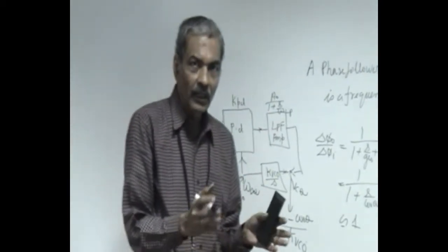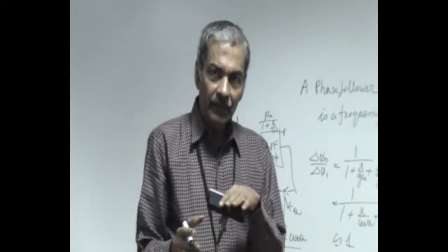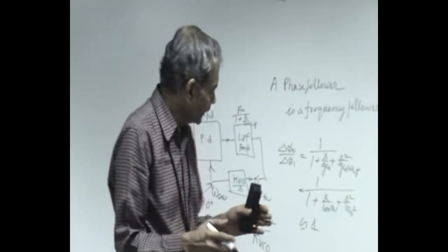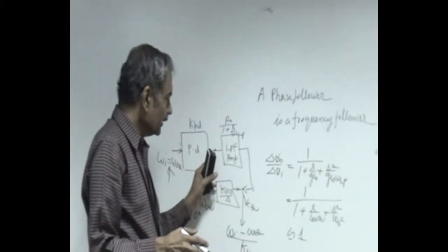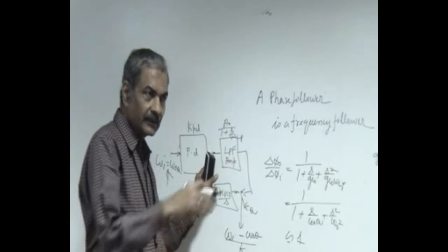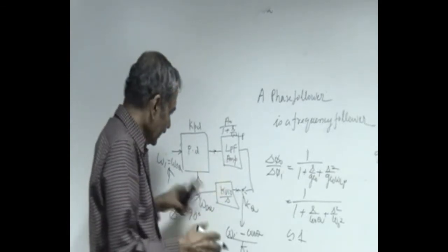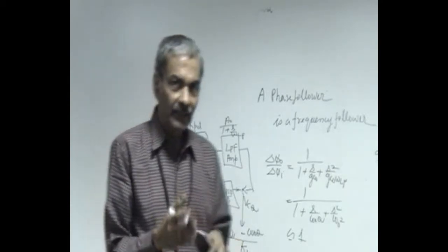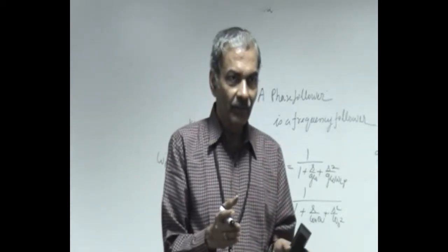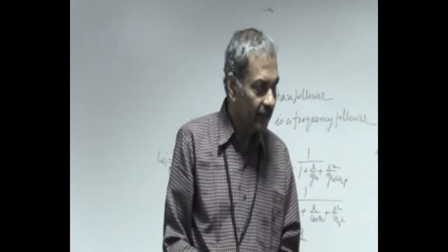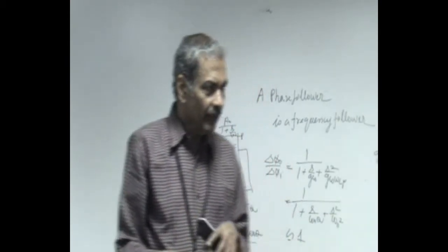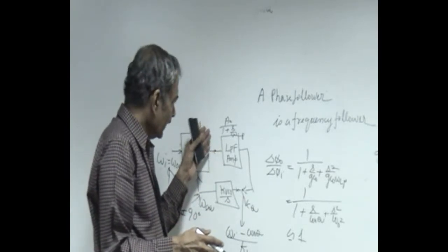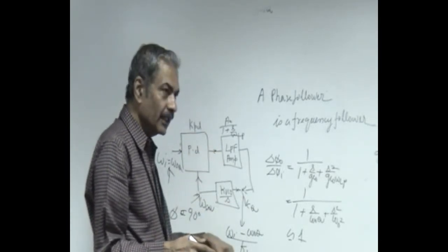This can go on until the phase change can no more get followed, because the sensitivity here keeps on decreasing as it is a cos phi. When it is changing from pi by 2, the phase change here, which is the result of some average, is going to be cos phi equal to that finite DC value. So that will keep on changing until it reaches a maximum on one side and a minimum on the other side.